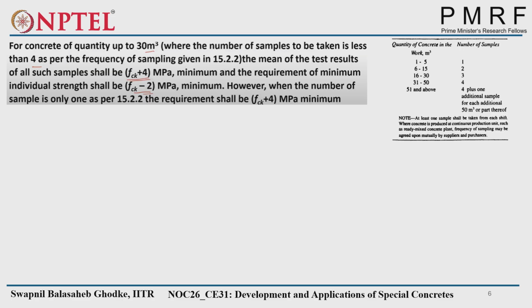Suppose one ready mix batch is coming, you collect some samples from there, and from another batch coming later, or you can collect all the samples from one batch. That is also important. So quality control is based on the experience of the quality control engineer also. But it's very important because concrete varies from batch to batch.